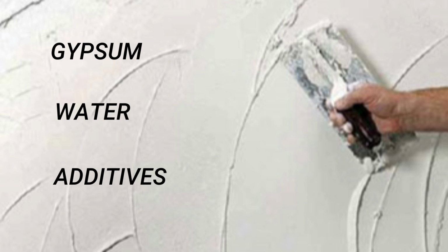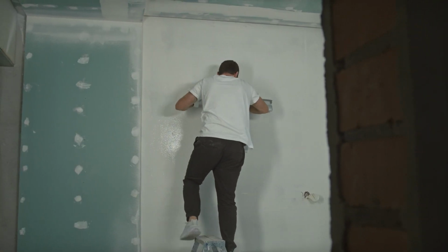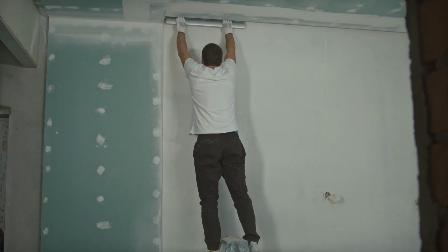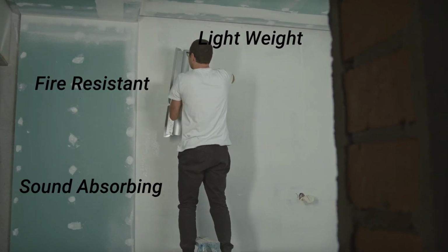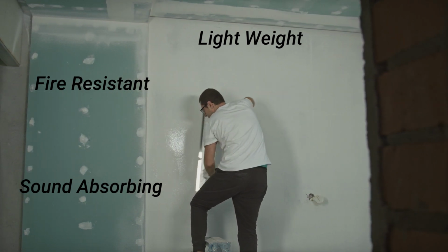The last component is additives. These additives are sometimes added to gypsum plaster to improve its properties. For example, retarders are added to slow down the setting time and hardeners are added to increase the strength. The properties of gypsum plaster depend upon the type of gypsum used, the amount of water added, and additives used. In general, gypsum plaster is a lightweight, fire resistant, and sound absorbing material. It is also relatively easy to work with and can be applied to a variety of surfaces.